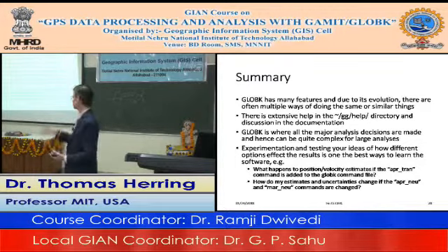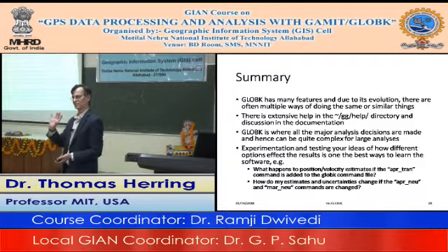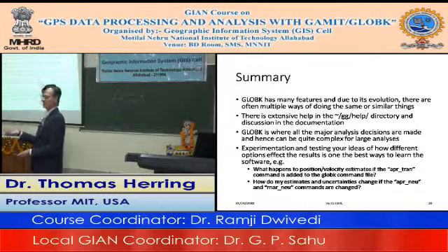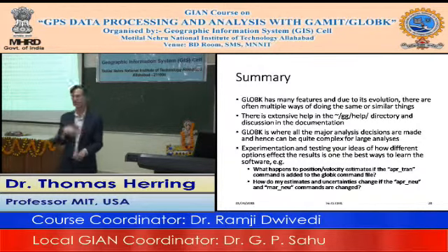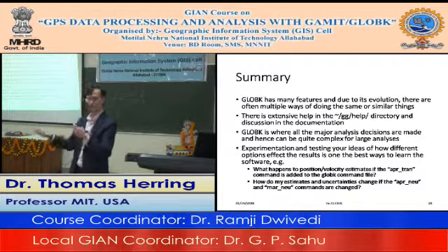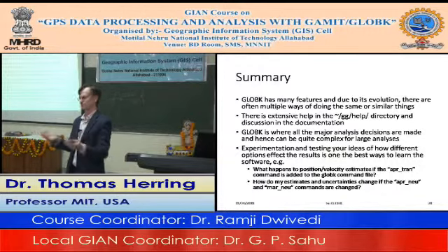But much of this, when you're doing data analysis of this type, agreement really is relative to how small the uncertainty is. So if you can only determine something to a meter, and you see a 10 centimeter difference when you do it different ways, to me that's in the noise of the estimate itself. If it's good to a millimeter, you expect to see less than a millimeter differences.